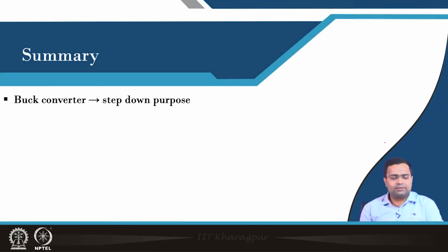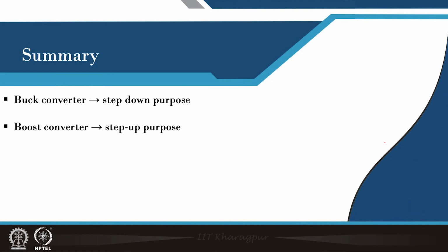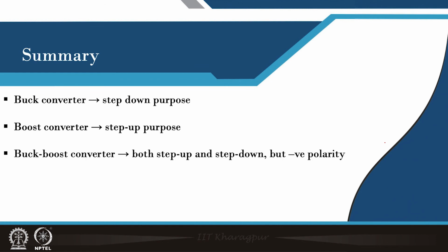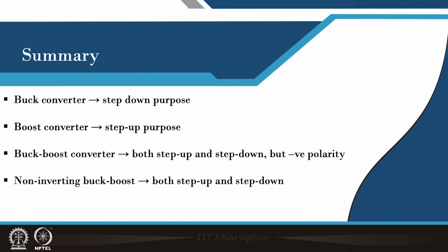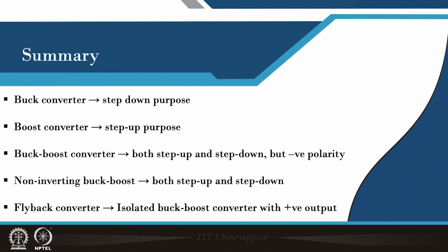So in summary, we have discussed the buck converter, for step down purpose, and the boost converter, for step up purpose. We have discussed the buck boost converter, for both step up and step down purpose, but with negative polarity. We discussed the non-inverting buck boost converter, and we have also discussed some basic isolated DC-DC converter architectures. So with this, we will move to the other lecture on modulation techniques and steady state analysis. For today, this is sufficient.